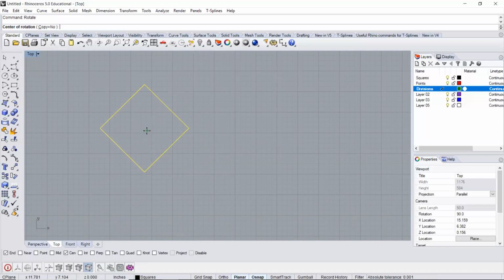I could choose my center of rotation. So this time I'm going to go from the center point. So I'll go ahead and just hover towards the outer edge of my object. And again, that's how I would access my center point. Unintuitively, you don't just go to the center of the object, you have to go to its edges. And I'll go ahead and select once I see the CEN tag pop up next to my cursor. So I'll click to place that.